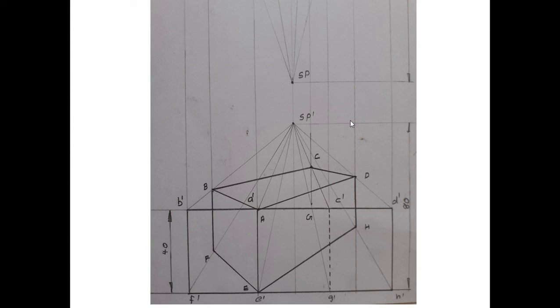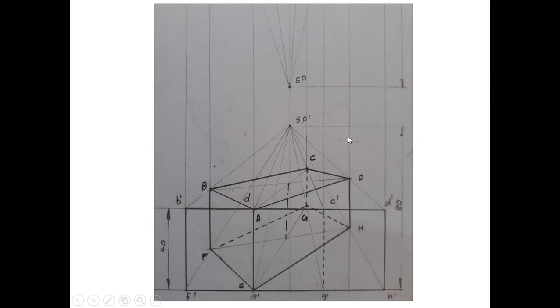Now after that you just do one thing. The CG will be invisible in this case, because CG is coming behind, and the station point lies in the same plane passing through the centroid. So the line CG, or the point G, will be invisible, or all the lines CG, FG and HG will be invisible in this case. You mark those lines using dotted lines, and also locate the centroid. For that you connect two opposite corners of the top face and bottom face. You get the centroid. Just connect that using the axis, the chain line. So finally you'll get this.